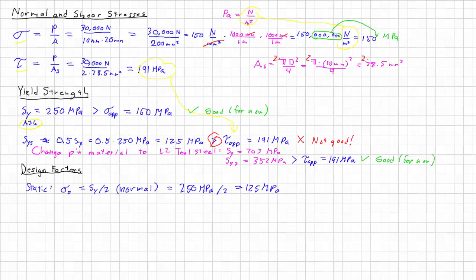So in order to compare it, we want our design stress greater than the applied stress. But as we found out up here, our applied stress is 150 megapascals. And guess what? That means it's not good.